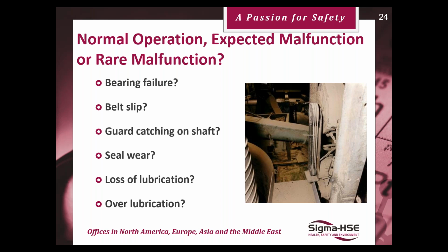There can also be over lubrication. There could be other things to consider, for example, static electricity. Probably not mentioned this. Maybe the belt is not anti-static. It can be isolated, and it could produce small sparks. And maybe this equipment is in a vapor atmosphere, so it could be a potential ignition source. So for a recommendation on this photo, I definitely recommend they check if the belts are anti-static, if it's in a vapor zone.